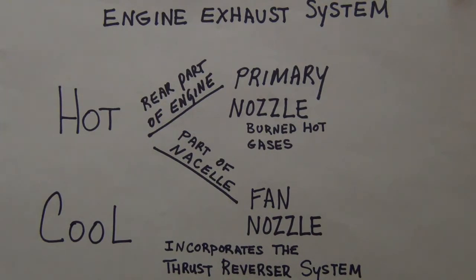You want to know your critical point: if you go below 22 psi, you've got a serious problem, something that has to be looked at. Here you need a certain minimum hydraulic pressure to release the latches. Just to have an awareness, there's a range, somewhere between 700 and 900 psi. So just have an idea of that in your head.